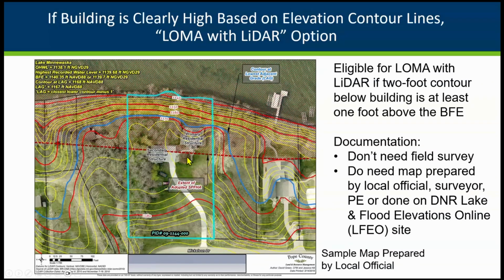And so this is a situation where FEMA, it's been over 10 years now. When we started getting the LIDAR and having these contours available, we argued to FEMA that people shouldn't have to pay for a survey when they're tens of feet above the base flood elevation. And FEMA agreed, and we worked out this process where you look for the contour that's not touching the building and is below the building.